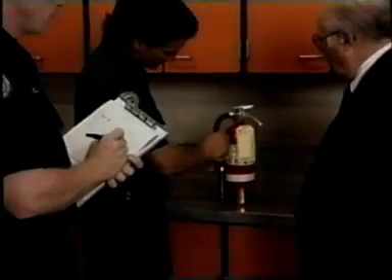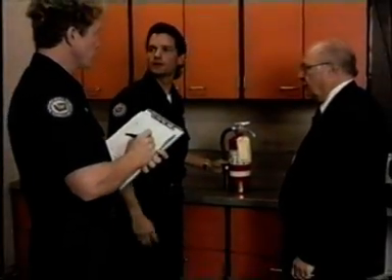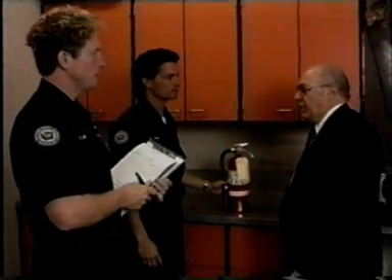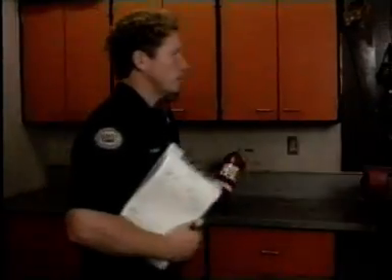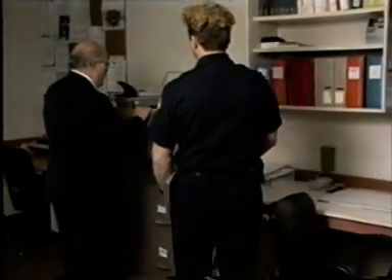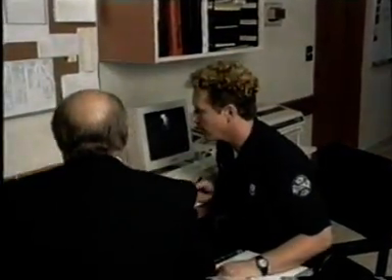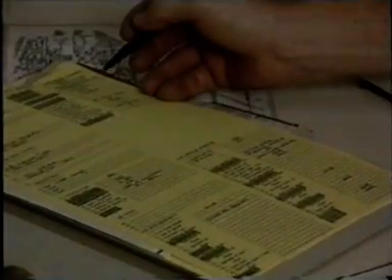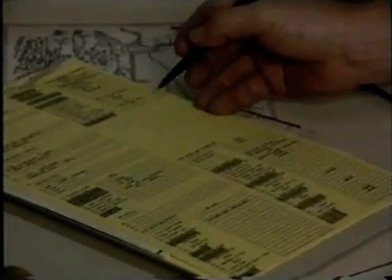Determine the user's ability to operate by conducting training for employees or other occupants that may be first on the scene. Fire extinguisher maintenance is the responsibility of the property owner. Fire extinguishers should be thoroughly inspected at least once a year. Some types of extinguishers will require a thorough examination by a manufacturer's representative at regular intervals. Owners should keep records of maintenance and inspections, and fire service inspectors should review these records during the visit.